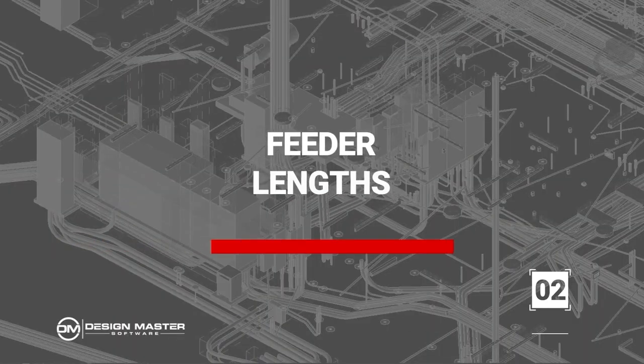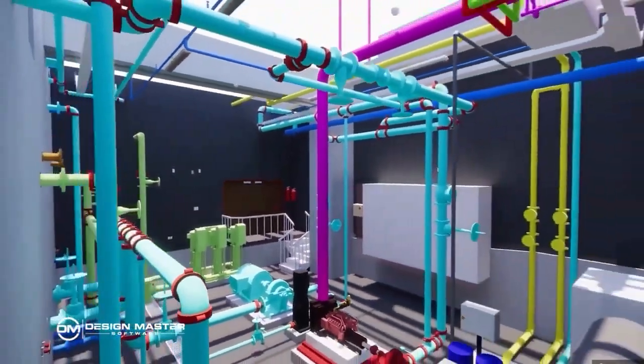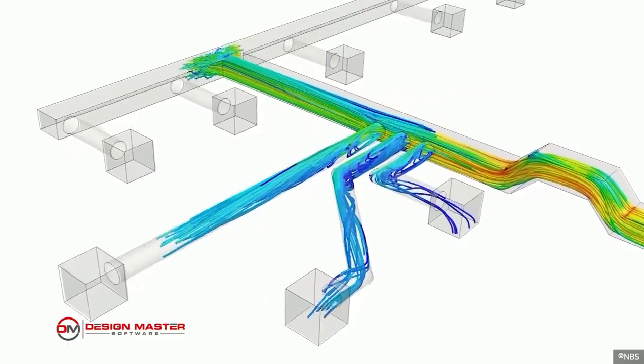Once you have your panels, then you have the distances between those panels. Again, in building information modeling, you are locating those panels in your model, so you know where they are all located. You can use those locations to calculate those distances. To get a true length, you're going to need to model your conduit. You're probably not going to be doing that, particularly in the beginning of your design stages, but just based upon their locations and either doing a straight line calculation or doing some right angles to account for the walls of the building, you can get something that's going to be close enough for a fault analysis.